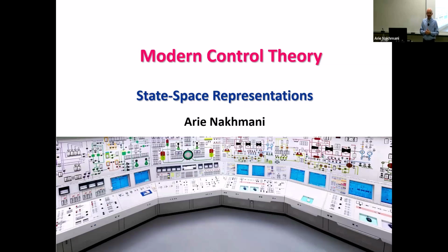We discovered the surprising fact that eigenvalues of the system are actually poles of the system, which is exactly the same thing. And this means that now we will be talking only about eigenvalues of the system, because this is what you get from the matrix A. So taking eigenvalues of the matrix A, they will be poles of the system in open loop, in closed loop, when you will have the controller closing the loop, and so on. So we will just deal with these eigenvalues all the time because they will be poles of the system.